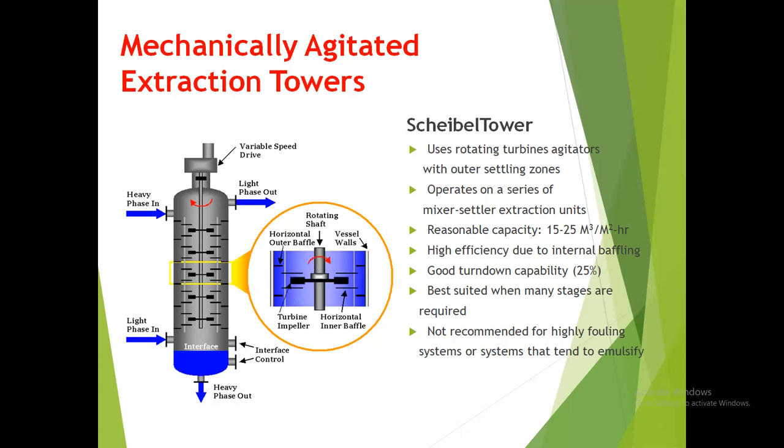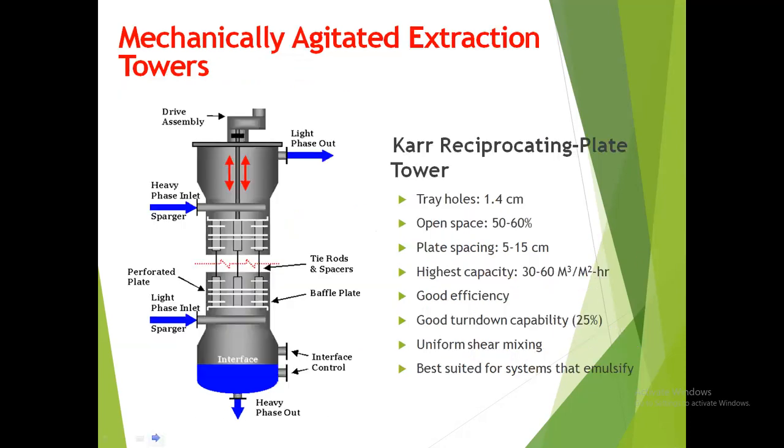Not recommended though for highly fouling systems or systems that tend to emulsify, or shall I say colloidal systems, they tend to emulsify. So this particular extraction tower is not recommended for such systems.